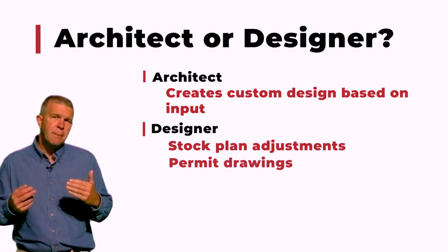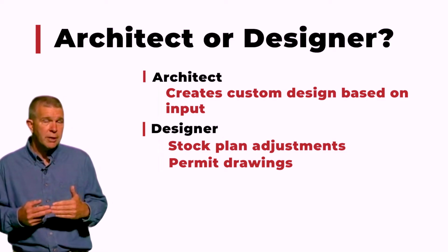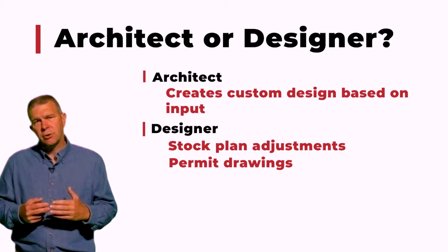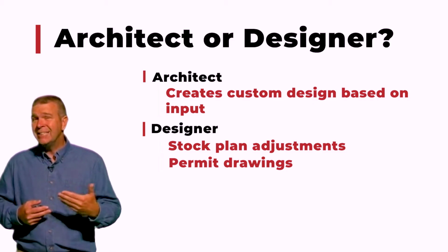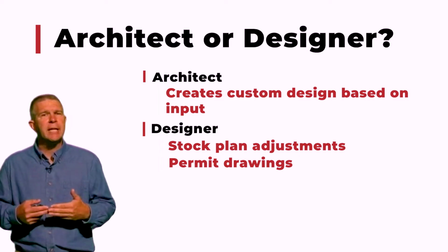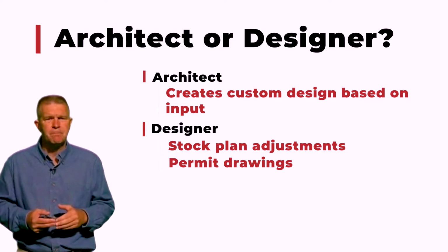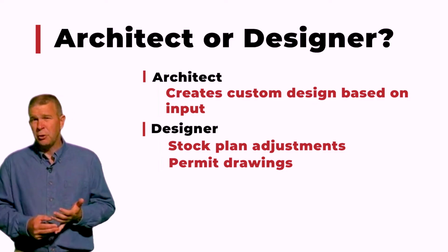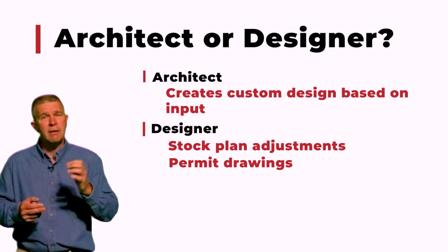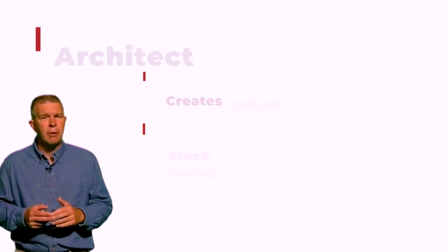It is the SIP providers, the manufacturers, and the people that do SIP-specific drawings that we're going to be talking about a lot that have the knowledge of what SIPs do, how they go together, and what engineering capacities they have to meet certain criteria, such that they can utilize SIPs to their most effective optimization. The designers have the ability to do permit drawings. They have the ability to take the architect's drawings and convert them over to a SIP drawing, and we're going to talk about that later on in the program.